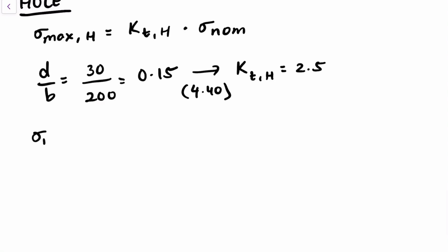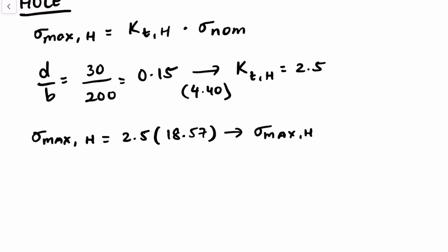So sigma max at the hole is equal to 2.5 times the nominal stress, 18.57. So sigma max at the hole is equal to 46.4 megapascals.